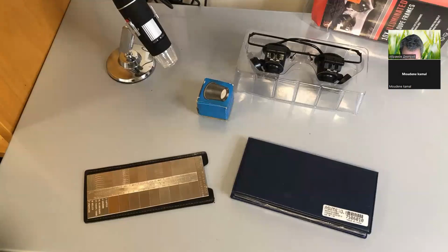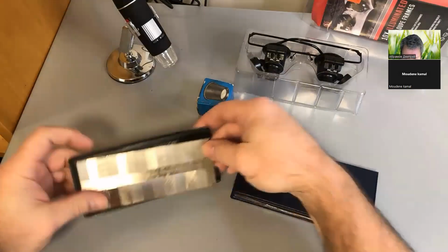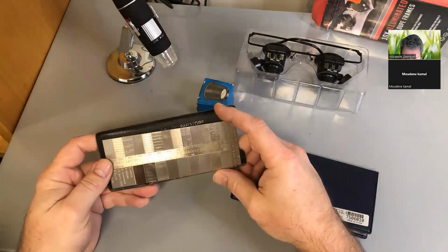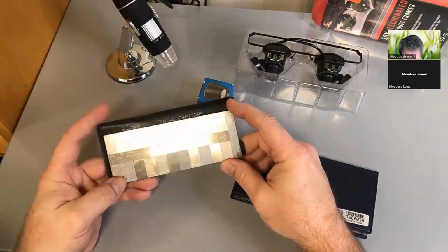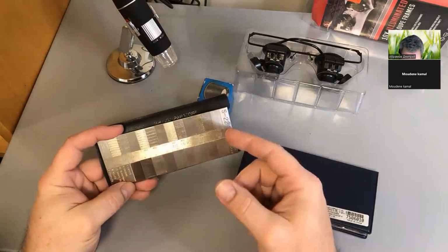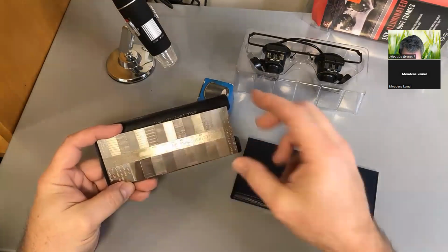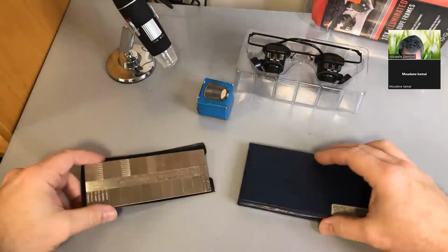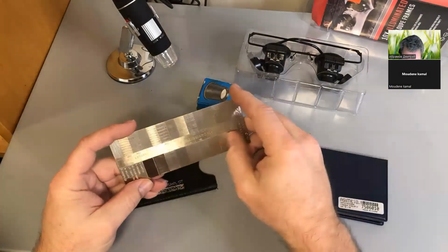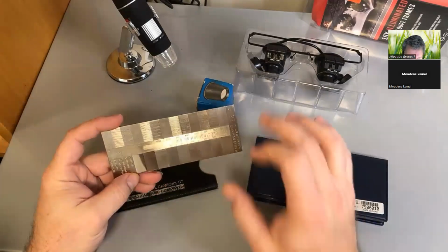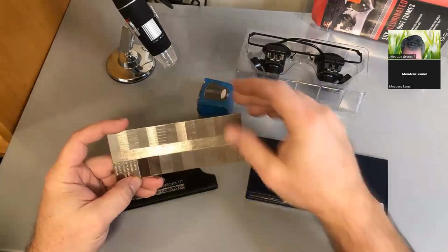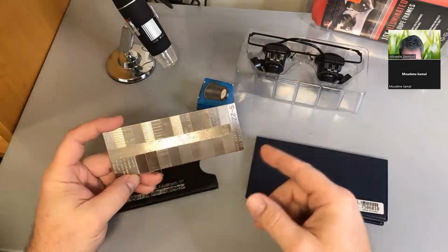Visual surface finish comparator. Let's talk about the visual surface roughness comparator. And that's what we have right here. This guy's an awesome visual tool or visual reference for apprentices because it allows them to see right away what type of finish they're getting while they're machining, which is kind of cool. These are not to be touched. Everyone wants to touch them. Oh, I'm running my fingernail up and down them. You're not going to get a super true reading by running your fingernail up and down because they have a bit of a coating on them.